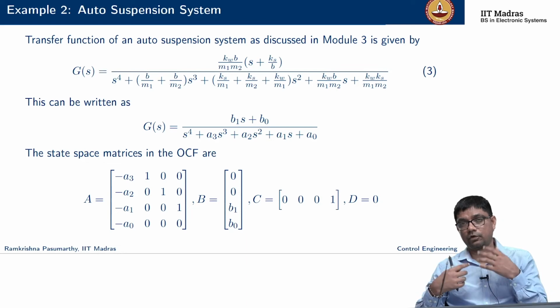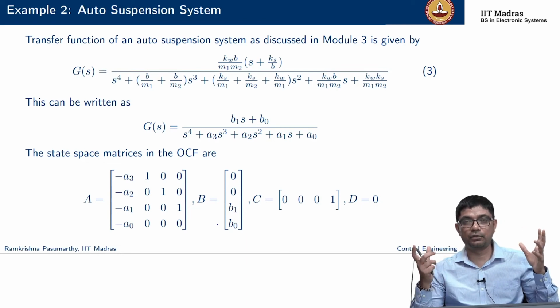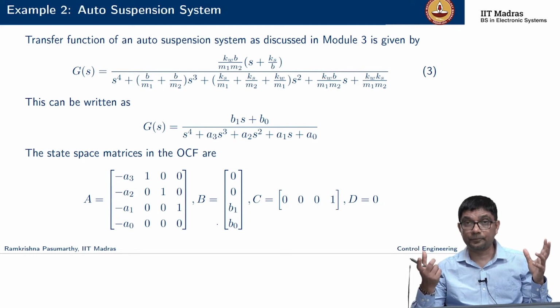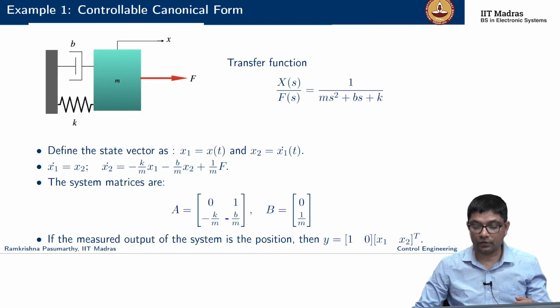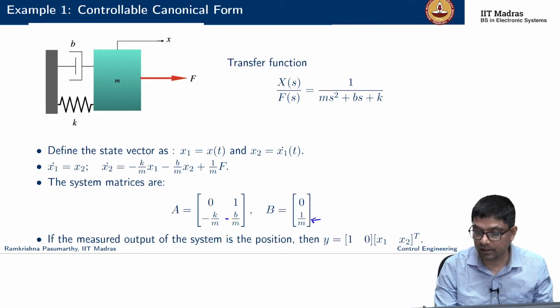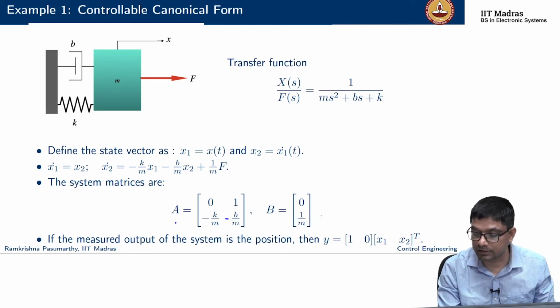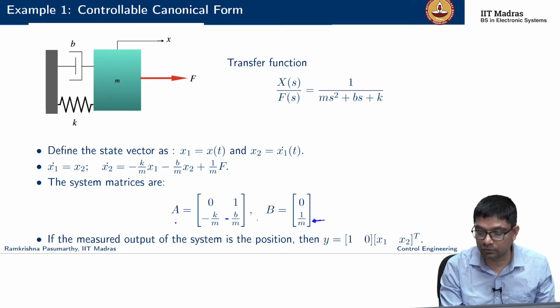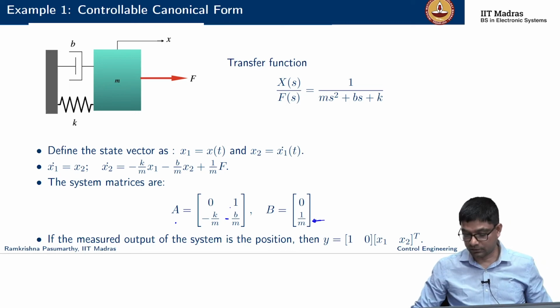And if you look at what we had talked about in the DC motor, through the voltage I am able to control the speed, right. So if I write in a controllable canonical form, this is where my input enters. Okay, this is now the DC motor example. Because here the control input enters through the acceleration, but it also controls the velocity and therefore the position also.